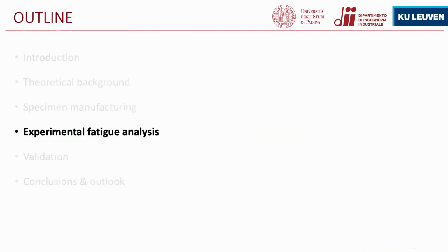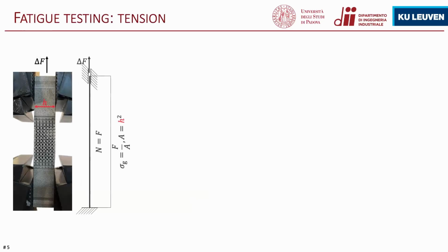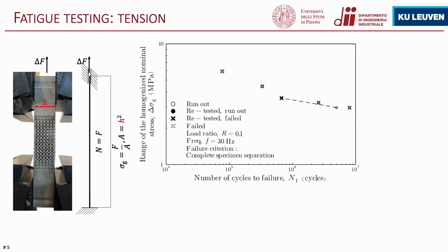So moving on to the experimental fatigue analysis, tests were performed under remote tension, so a very simple loading condition. Here you can see the static scheme of the test I'm conducting, which is again very simple due to the simplicity of the loading condition in testing. And here you can see the S-N data obtained experimentally, the preliminary one. I'm still carrying out some more tests, where on the x-axis, we have the number of cycles to failure.